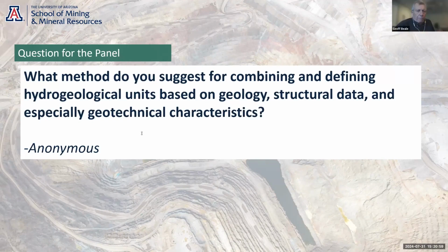Okay, so maybe I'll take that one first. The first thing to look at on the hydrogeological side is the response to hydraulic stresses, i.e., look at the pore pressure data, look at the water level data, and see how the piezometers installed in different hydrogeological units behave to various stresses.